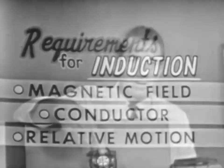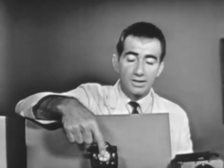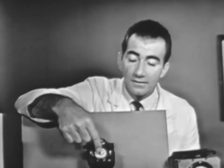Exactly. So if we increase the relative motion, we increase the rate or the frequency at which the conductors are cut by the flux lines of the rotating field. The greater the frequency of cutting, the more the current in the rotor, and the stronger the magnet. Now, that's why the rotor can continue to turn the fan.